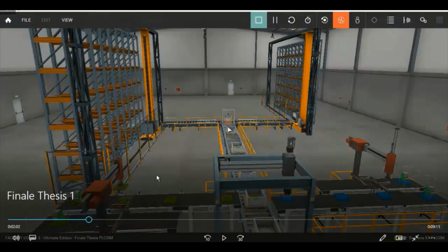So when we pick this one, obviously if it's all full, this conveyor is going to stop, and same process as I stated before, everything is going to stop. Obviously it's going to stop moving because we don't have any storage areas, so this crane is going to command the one previous to it to stop working, and everything is related, so it's all going to stop.